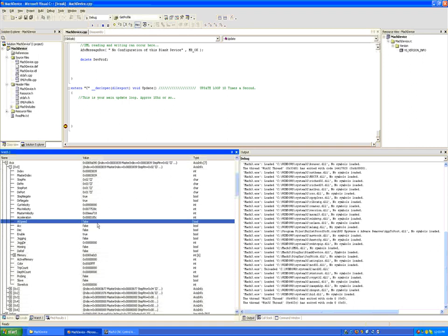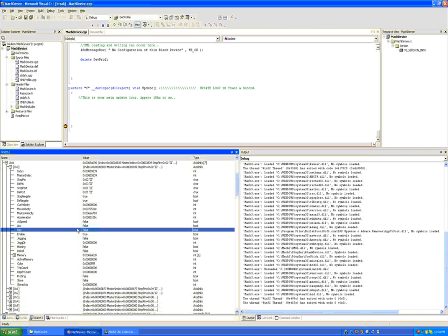At speed tells us if this axis is now up to full speed, so it's finished its acceleration phases. We have accelerate and decelerate variables, which tell us whether or not our axis is accelerating or decelerating, and these are actually trip variables, which can tell an axis to start decelerating or accelerating up to a master velocity limit.